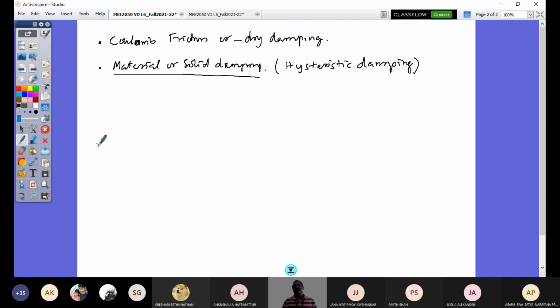So we see that vibration is due to rigid mass, but you can also see the vibration due to deformation of the mass. For example, you see the tire vibration. Tire vibration can have vibration as a rigid mass without any deformation. Tire vibration can also be looked at as a vibration due to deformation of the carcass part of your tire. So that would be flexing. So that is a deformation. So the deformation also can cause vibration.